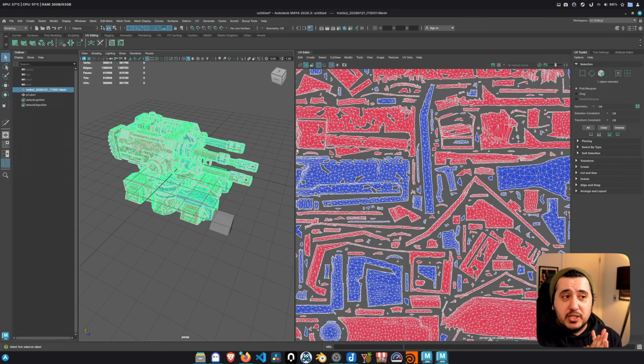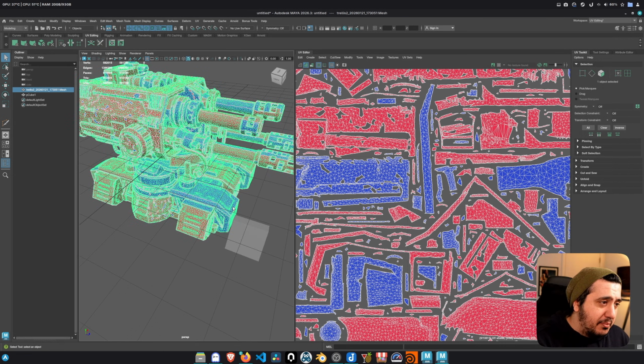Why is UV unwrapping terrible? Because it is 2026 and we are still doing this UV unwrapping manually. Sometimes UV unwrapping can take more time than modeling whatever you model. It's a boring process. Stitching edges together, making sure that everything is in its own island properly, and you need to think about the texturing side. You can create a UV shell thinking about a material that's going to be on that shape, and you can create that UV island according to that, etc.